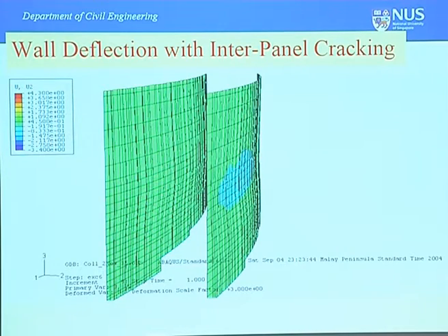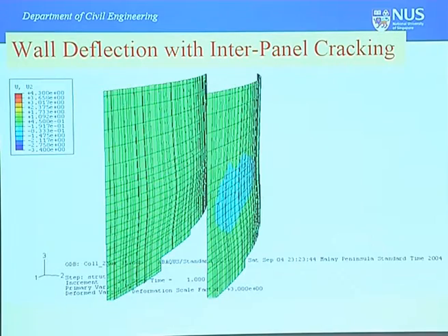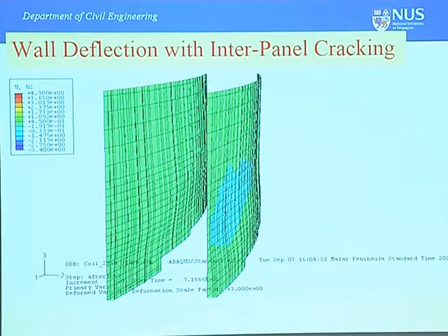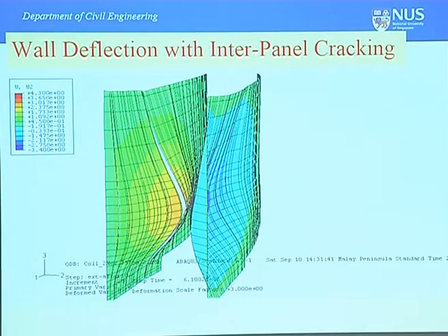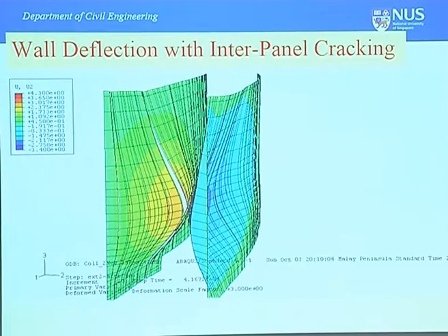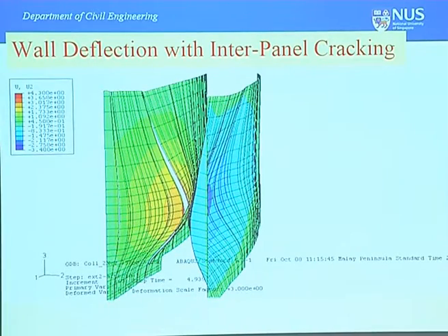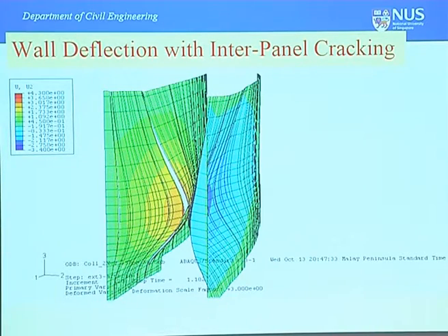The unintended effect is, yesterday I told you about the south wall. You can see the south wall is on the convex side of the bend. So when it comes in, the wall line is breaking up. It's actually pulling the wall line apart. And so as a result, you get tensile stress along that wall line, pulling it this way. And so therefore, there is the natural tendency to just break it up. You know? And that explains why the south wall is actually deflecting a lot more.